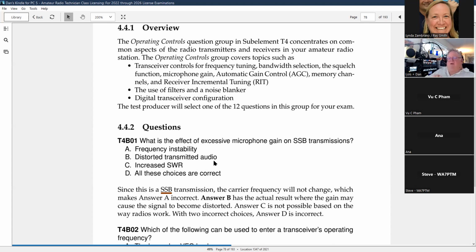You can imagine, if there's a wave of the frequency of your voice, if you go too loud, it goes up and then kind of gets stuck until it comes down, and that's called clipping. Speakers can do it; they just sound wrong, and you'll get distorted transmitted audio if you have too much microphone gain. That's the volume setting. Microphone gain, think of it as the volume setting for a microphone.